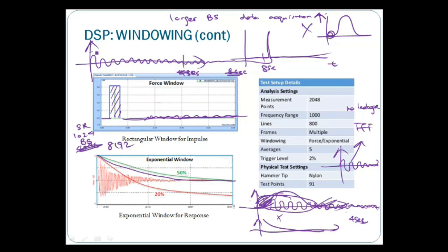So I can actually wait until 8 seconds, when it dies down to 0, then only I take it. Okay, then this thing will be sent to FFT. So of course, you will compromise on the time, but in this case, you can also achieve the signal without leakage, right? It can ensure that it ends at 0 by itself, not by forcing.